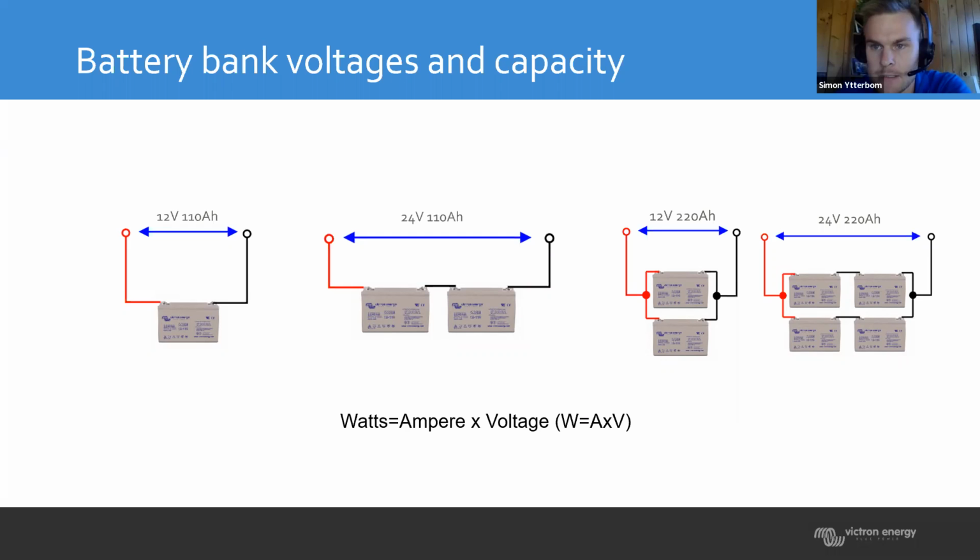It can be AC loads and DC loads, and to understand those better, it's easier to work in watts, because that's the true power measure regardless of the voltage, because the voltage and the amp hours are correlated to each other. Low voltage, high amps; generally high voltage, low amp hours. So converting it to watts is going to help you if you're designing or looking at your system.